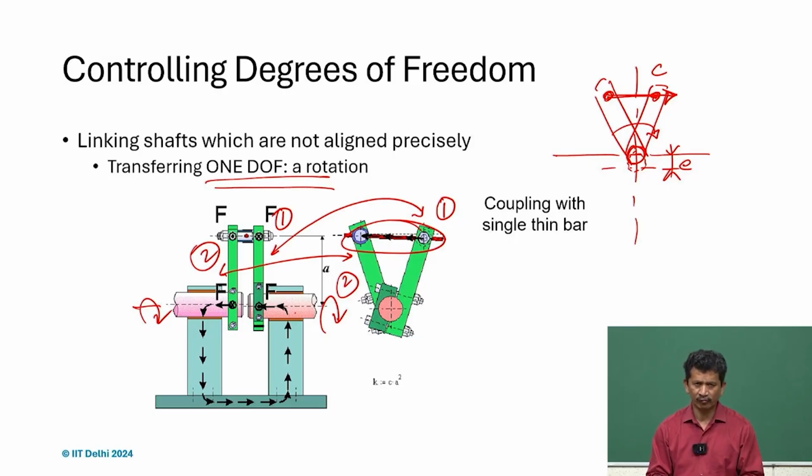So, this is one exercise, and if you have access to 3D printing or some other ways, you can machine it, and it is very simple: just insert a 1 millimeter diameter wire or even thinner, and get this kind of arm extension. You can provide the offset or misalignment between the two shafts by shifting the bearing locations, and you can test yourself that it's a very good solution.